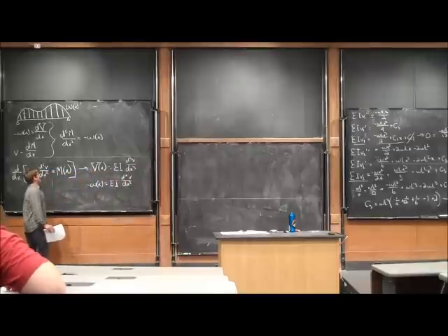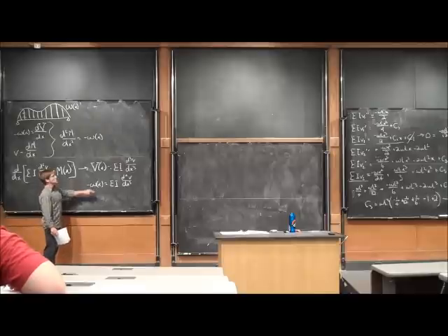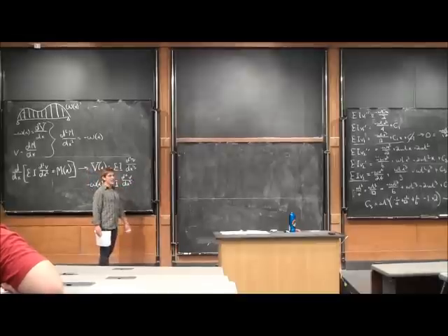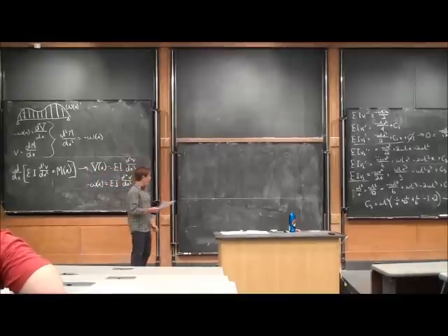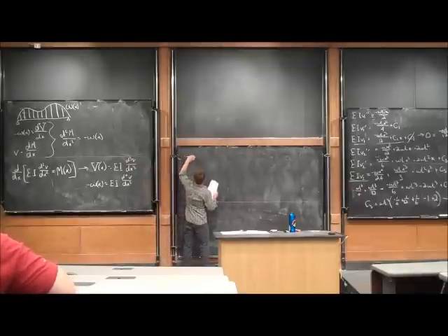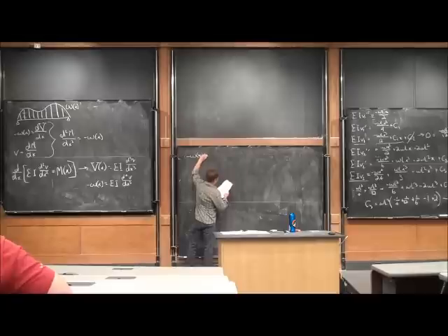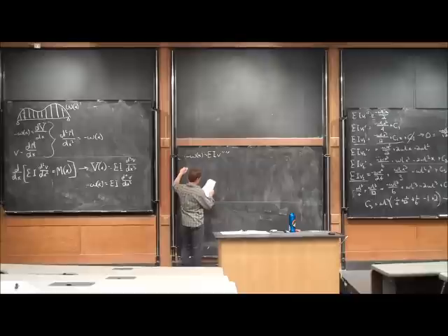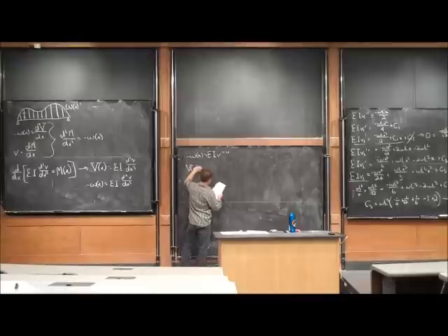So now, given we have a function that describes the loading, we can find the deflection at any x location along the beam. So, to summarize, we have the loading function is going to be equal to EI v with four primes. We have that the shear function is going to be the 3rd derivative of the deflection.